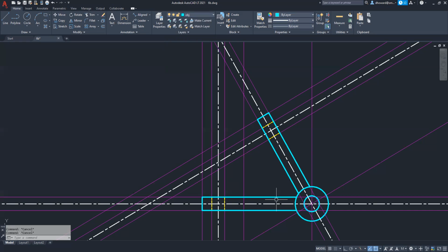And the next important dimension is from the top of the bottom arm here. So this line right here, upward, we are given an intersection point on this line that we just created. And it is 1 3/8. So again, it's right off the drawing. So if you offset 1 3/8 or 1.375, and it's just this horizontal line, the upper face of this lower arm.